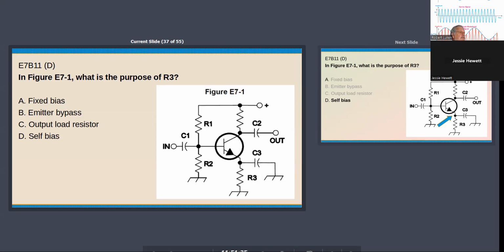True, but sometimes, depending on the characteristics, the transistor won't be perfectly linear. So you may shift the operating point one direction or the other to keep it in the linear range, and you may also restrict it. If you operated it from saturation to cutoff, you'd obviously have distortion at the cutoff and saturation ends. So you want to keep it in the middle, in a section of the operating point that's as linear as you can get it. It won't be perfect because they're real devices.